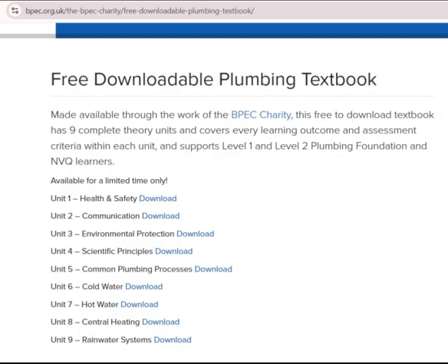Natural gas. Natural gas is the most widely used fuel for home and business heating and cooking in the UK. It is primarily a mixture of 5 gases. Methane CH4, 92%. Ethane C2H6, 3%. Propane C3H8, 3%. Butane C4H10, 1%. Nitrogen N2, 1%. Four of these gases, methane, ethane, propane and butane, are flammable. Nitrogen is inert. There are also traces of carbon dioxide, CO2, and hydrogen, H2, mixed in.